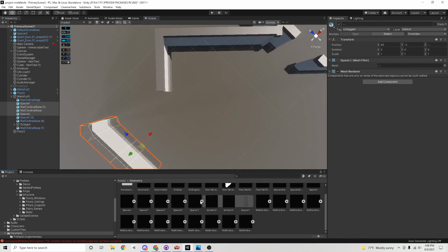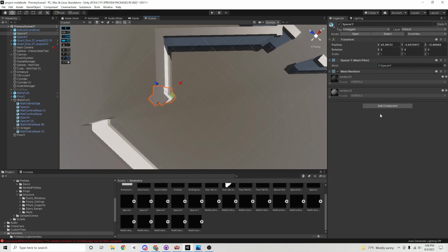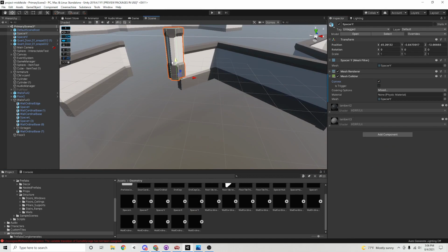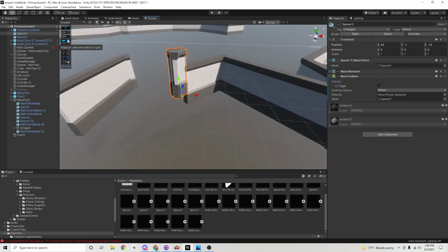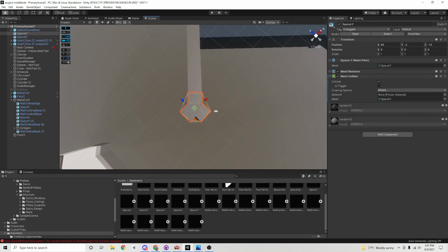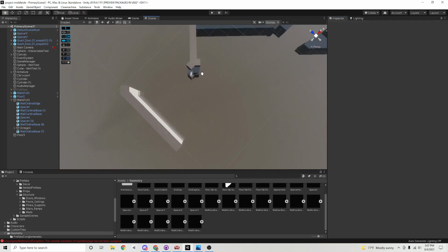So I'm going to grab a Y piece. Y pieces are some of the most frustrating ones to orient. You've got to go through all of the different transforms a lot of the time to get them in their precise orientation. Oops, I turned that off. Bam. And let us go through it. I believe it should be something like 135? Negative 135. There we go. So that's going to be our proper orientation.